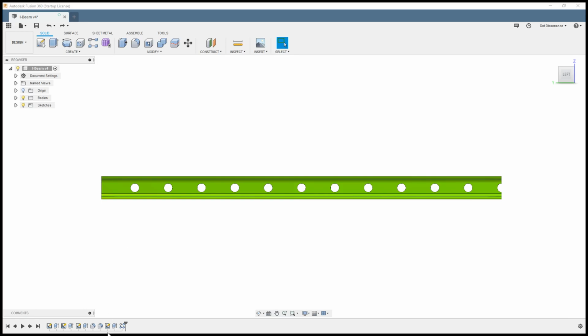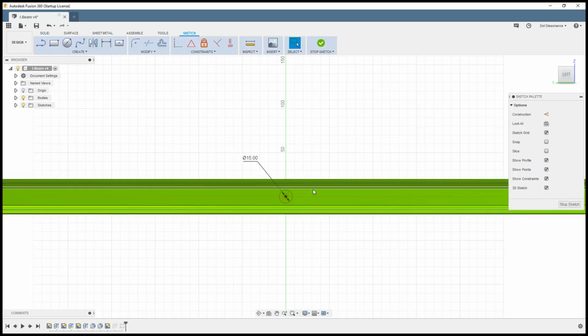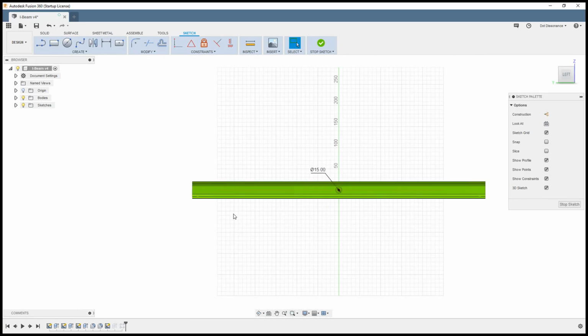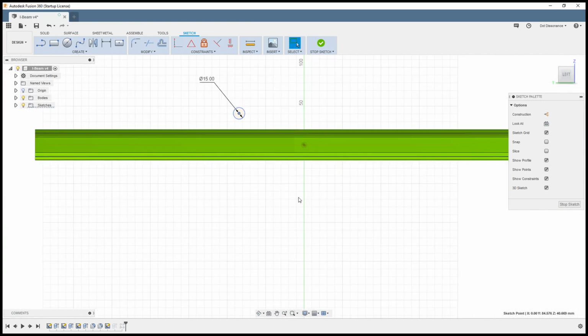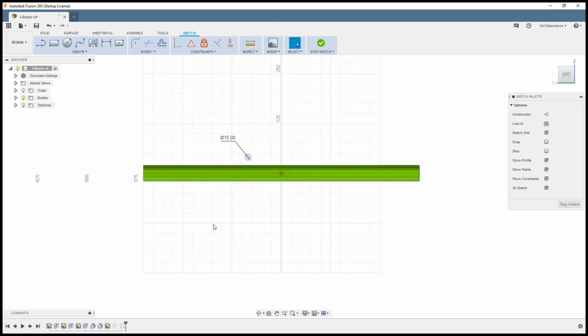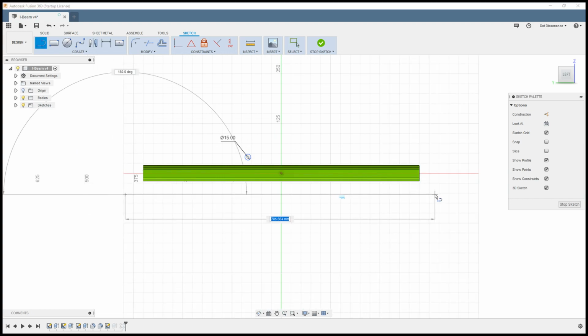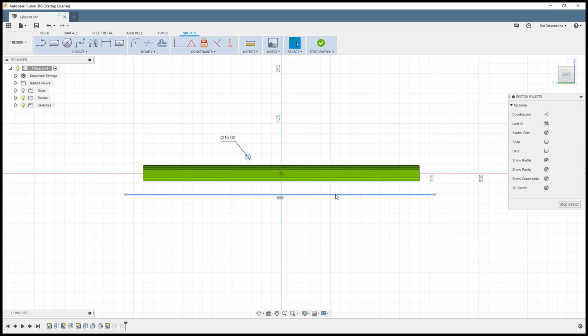Okay, so here is a way to go ahead and do this. So we're going to edit this sketch here, and I'll need a couple things first. So first, you can just delete and start over, but if you click there, then you can get the coincident constraint, and then we can delete that and just move this off to the side for a second. And then zoom out here, and I'm going to need a construction line. So we'll get that across there. We'll make it construction.